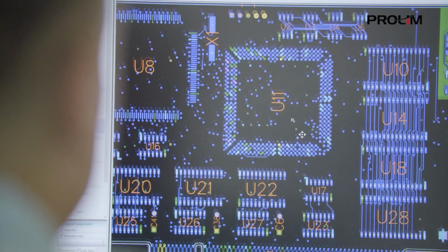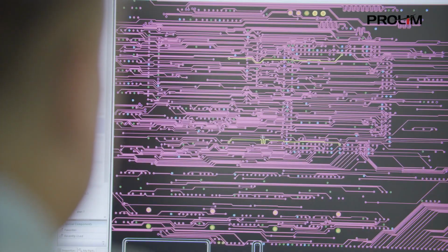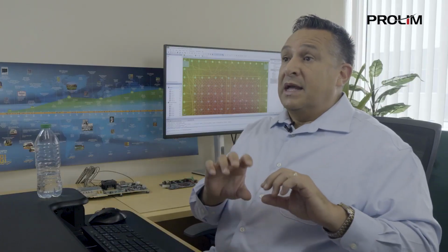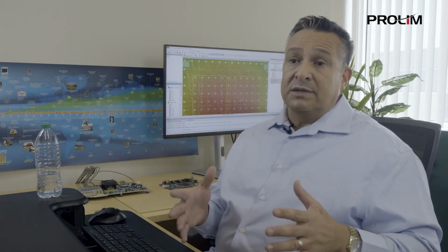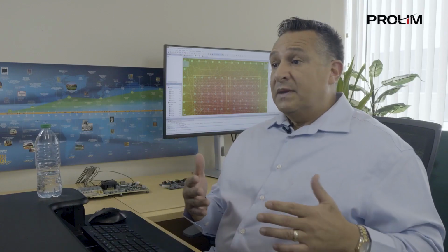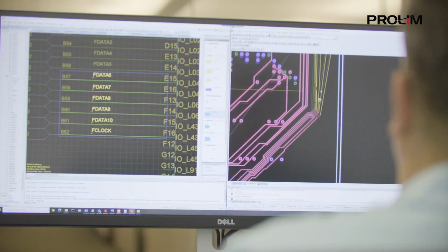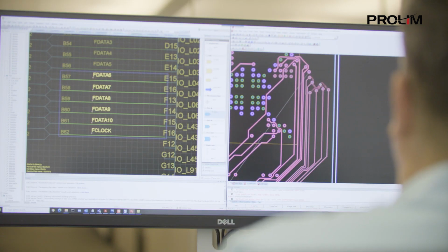Because when you think about a rigid flex design, you'd have a rigid section, a flex section, and then another rigid section. You could have multiple stackups: in the rigid area is one stackup, and in the flex area is a different stackup. So a lot of it can cause confusion, especially if you've never done it before. But our tools are more than capable of doing this all in one design database versus multiple databases. And these capabilities are commonly available in our tools today. So we need to stop doing workarounds from tools of the past, for our legacy designs.